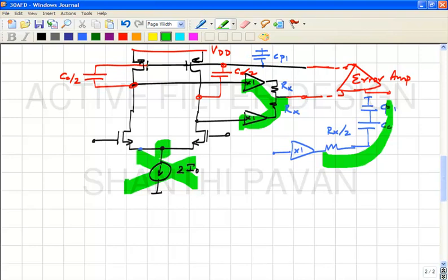The tail current source is giving you common mode rejection, okay? And as we all know, the tail current source also needs a minimum voltage across it in order for that tail thing to behave like a current source. Finally, that's being realized using transistors, correct? So this basically means that a part of the supply voltage is now needed to be dropped across the tail current. So some people say, hey, if the supply voltage is very low and you don't want to waste, within quotes, waste supply headroom across the current source, why bother with the current source? Why don't you